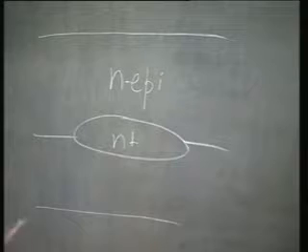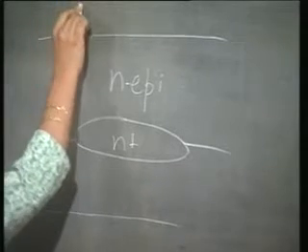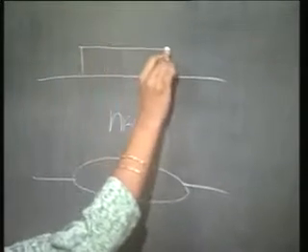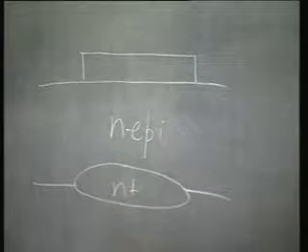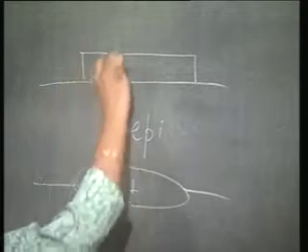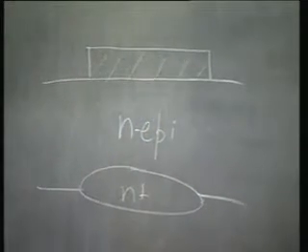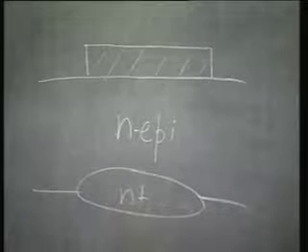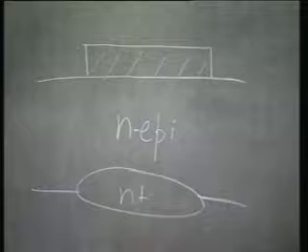Let us assume that the substrate was 100, the epi layer is also grown in the 100 orientation. Okay. Now let me protect my active region like this, okay, using oxide or photoresist or whatever. By a suitable protection, let me protect my active region and now let us subject it to an anisotropic etch. So, what will happen?